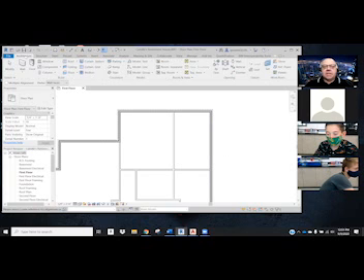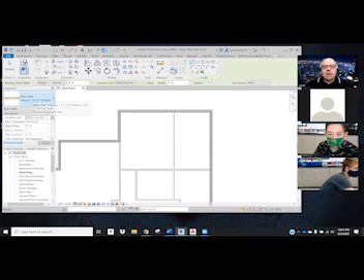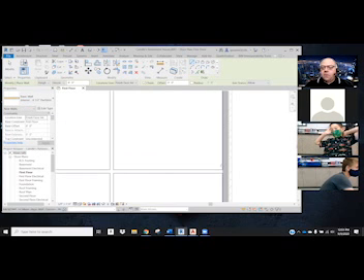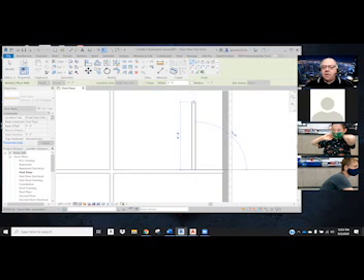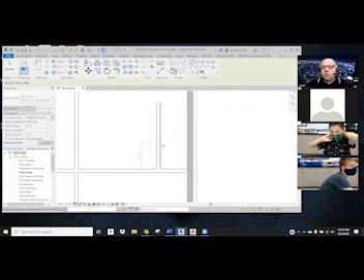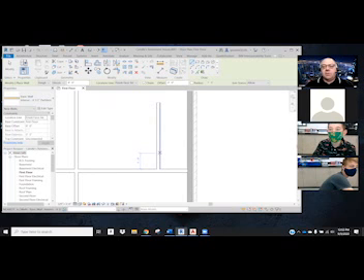What I'm going to do is I'm going to take a line, and I'm just going to take my basic partition wall, and for a water closet, I need 3 feet. So I'm just going to come in and drag a line in. I'm not going to worry about how far I go just yet because I'll do that later with you. And so I just put a wall in, and I need the wall from inside to inside to be at least 30 inches, preferably 36.